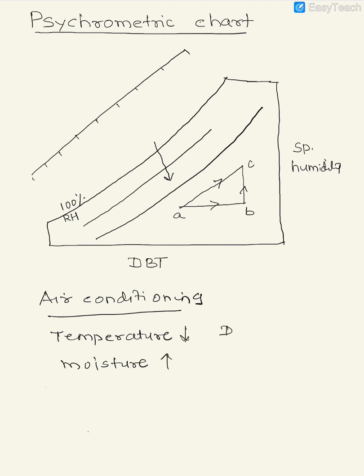So which process is then recommended? Decreasing the temperature means like this, and increasing the moisture content means like this. It means the process would be cooling and humidification.